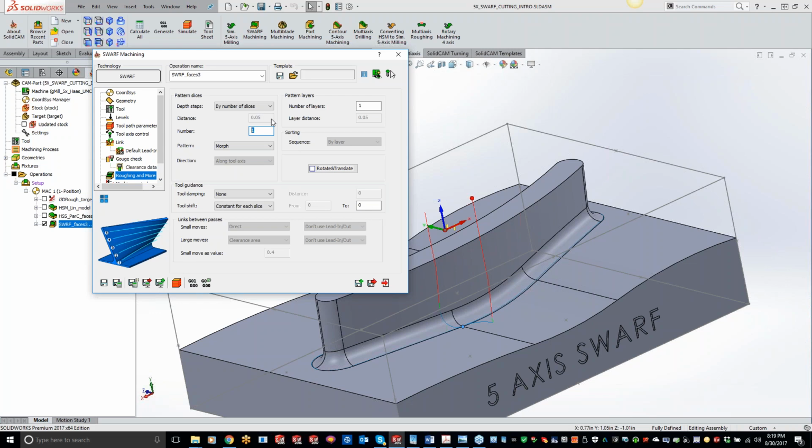Now, when we're actually doing our slice downs, we can have it set up to follow the curvature. So right now, it's set up to morph, but what we can do is do a step from the top where it's following the top contour. And if I can get this. So it's following the top contour, and then as it gets down to the floor, it's still keeping that top contour going. And same thing for the bottom. So you'll see right here, it's following the bottom contour, working its way out, going that way. My favorite is going to be the morph, just because when we're doing from bottom or top, we're getting a little bit of a waste of cut going on in there. Because you'll see as we get up to the top right here, this one's going to keep continuing out, where if we did a morph, it's going to change it, keeping it like how morph between boundary curves works. So it evens the lines out as it goes from the top to the bottom.